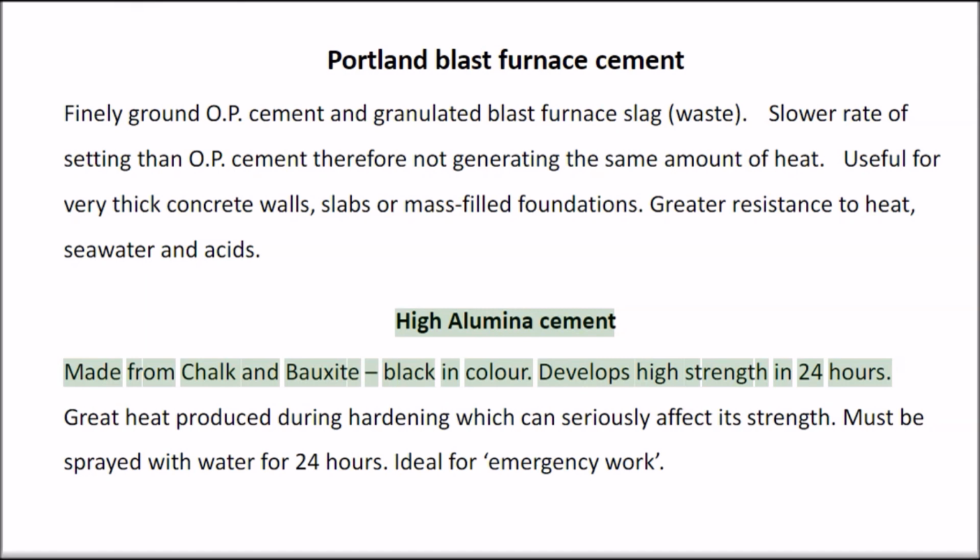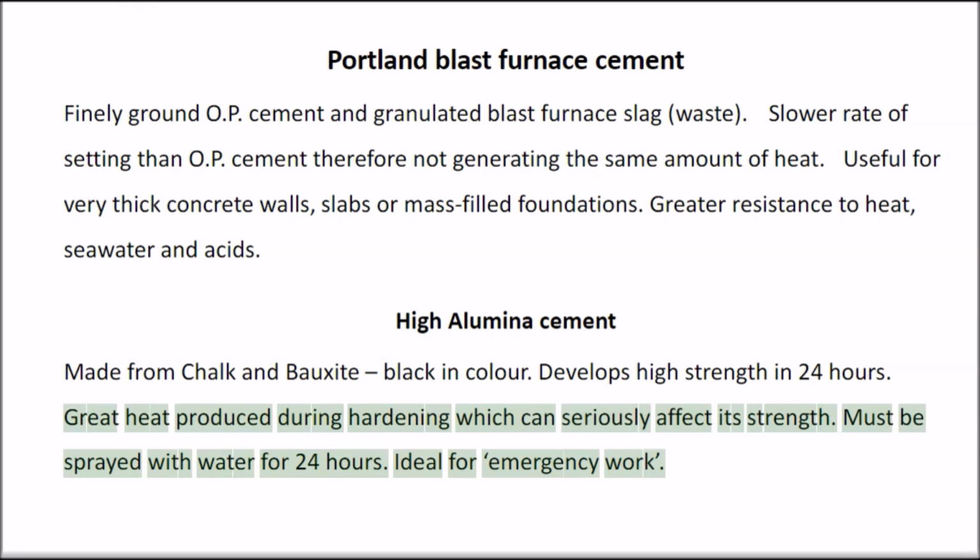High alumina cement, made from chalk and bauxite, black in color. Develops high strength in 24 hours. Great heat is produced during hardening, which can seriously affect its strength. Must be sprayed with water for 24 hours. Ideal for emergency work.